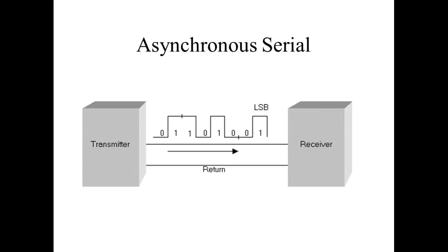It's called the baud rate or bits per second. So when we looked at that the other day, when it said 9600 baud, it means it was sending 9600 bits per second. So it means it was sending the bits out every 1/9600th of a second. Your receiver is going to receive at the same baud. So one thing that's got to be negotiated is the bit rate.